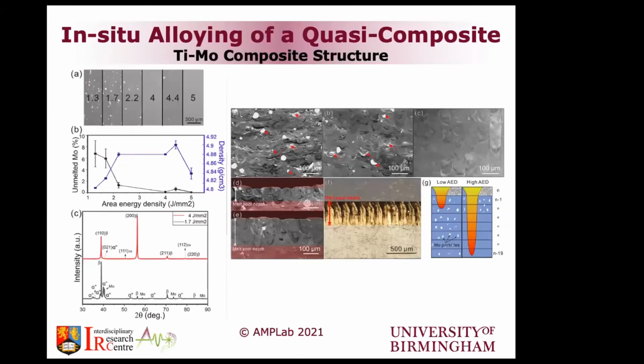One of the other ideas we had was relying on in situ alloying. So we did a project on titanium 12% moly. This is an alloy that we use, well, a model alloy for medical applications. And we rely on in situ alloying because sometimes it can be difficult to buy this alloy. And what we found was that we can use the heat input to the level that we can blend aluminum, titanium and moly and homogenize the chemistry to a large level.